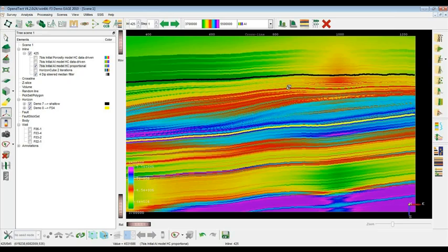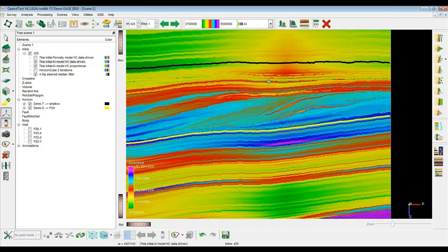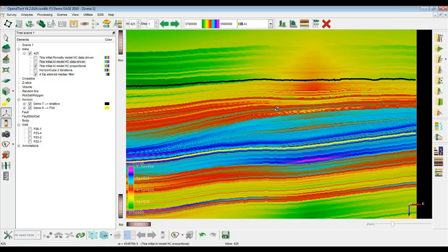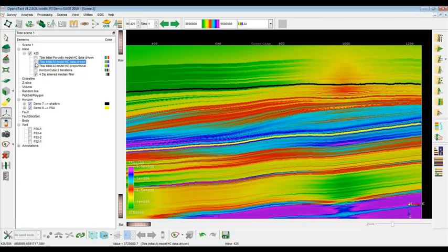And so here you can see, I'll toggle off a few times, the main major difference between a proportional slicing, so the usual impedance model, and the data-driven HorizonCube-driven impedance model. And as you can see in the range of the HorizonCube, we have a much better description of the geology and of the layers that actually honor the geology as compared to the standard case.